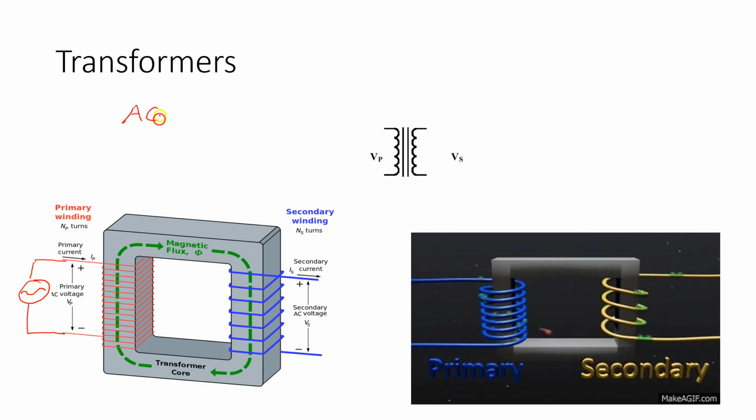Alternating current is the same thing as what we call AC, and the schematic for that is simply a circle with a wave inside of it, showing that it's alternating. So that's your power source. And this side will be the positive, this side will be the negative, right? Now, if you know anything about alternating current, it moves back and forth. The flow of the current reverses. So at one point, the current will be flowing in this direction. Then another time, it's going to flow in the opposite direction, as you can see right here.